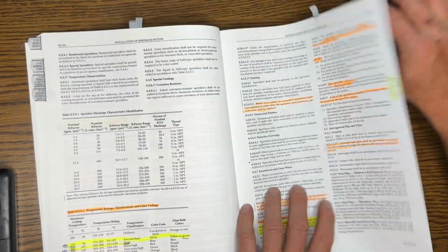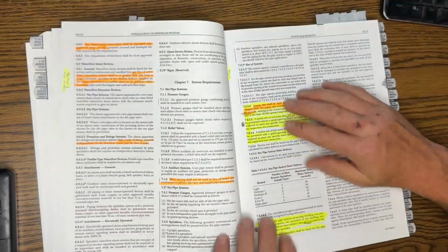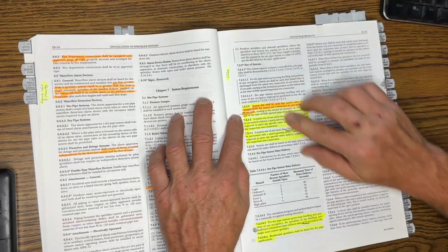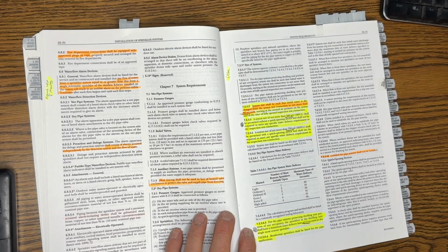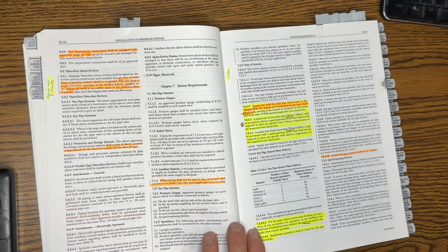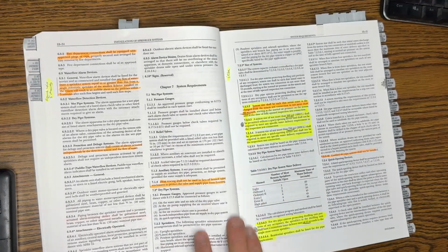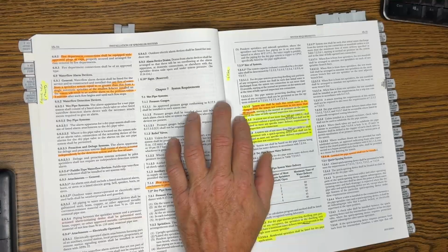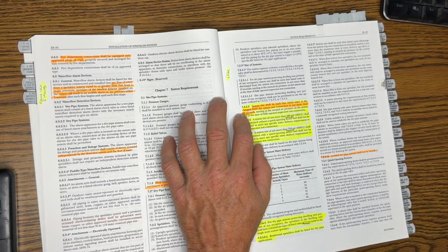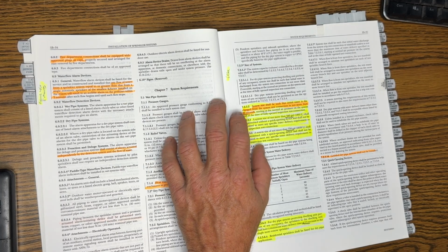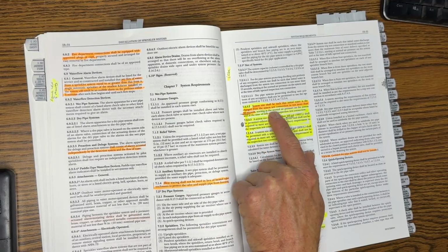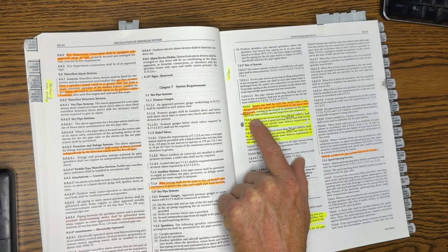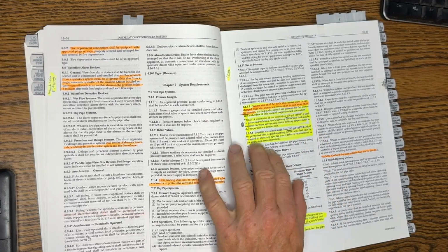Let's jump through here. Next one is 7232. There are two questions referenced on this page. The question was, does a dry pipe system always require water delivery within 60 seconds? And if you look here, system size should be such that water is discharged from the system test connector in not more than 60 seconds. But there are allowances.